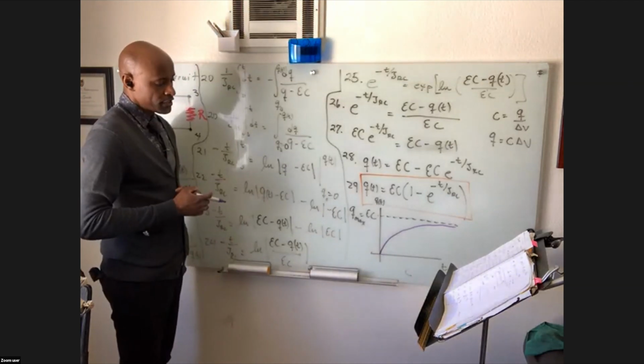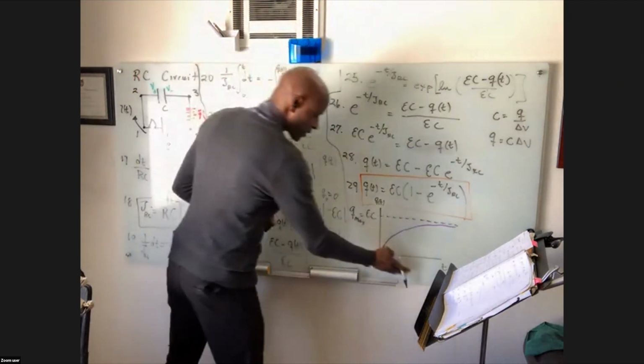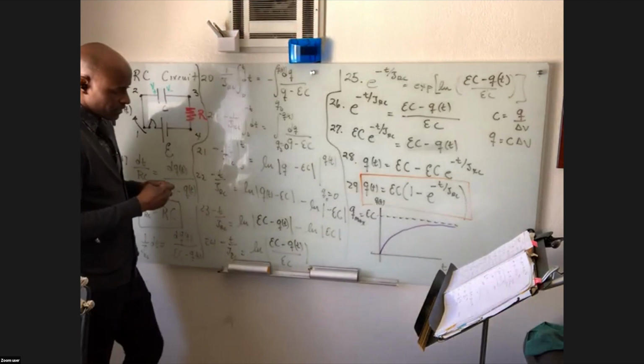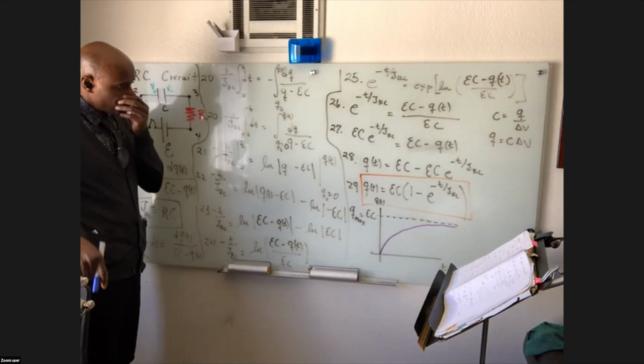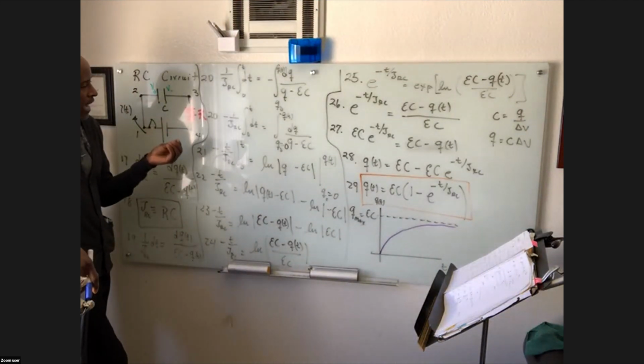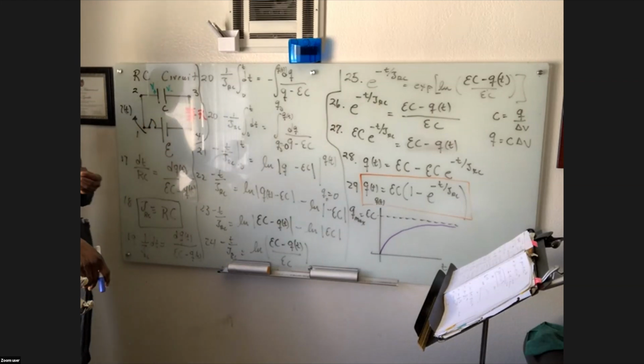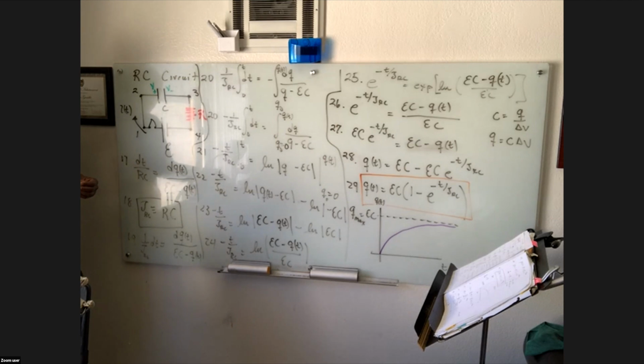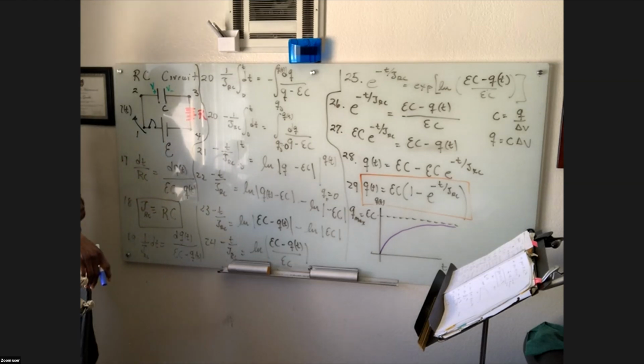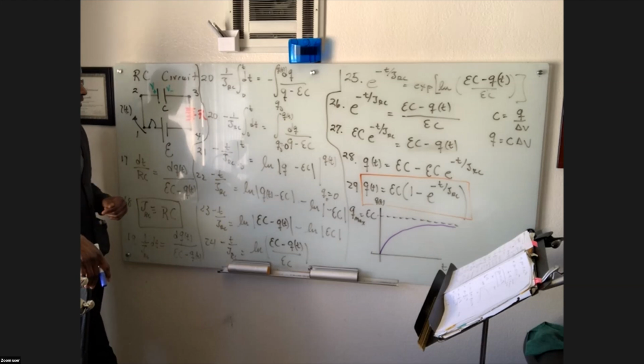But that's where the time constant gets its relevance, because first of all, we can control the time constant of the circuit. We can control how much time it will take for this capacitor to charge, because we control the value of the capacitor and the resistance. Understanding what those values are, we're going to know the time constant associated with the circuit just by choosing our resistor and our capacitance. This is something that's done in the lab. We work with this a lot. It's kind of a great lab.